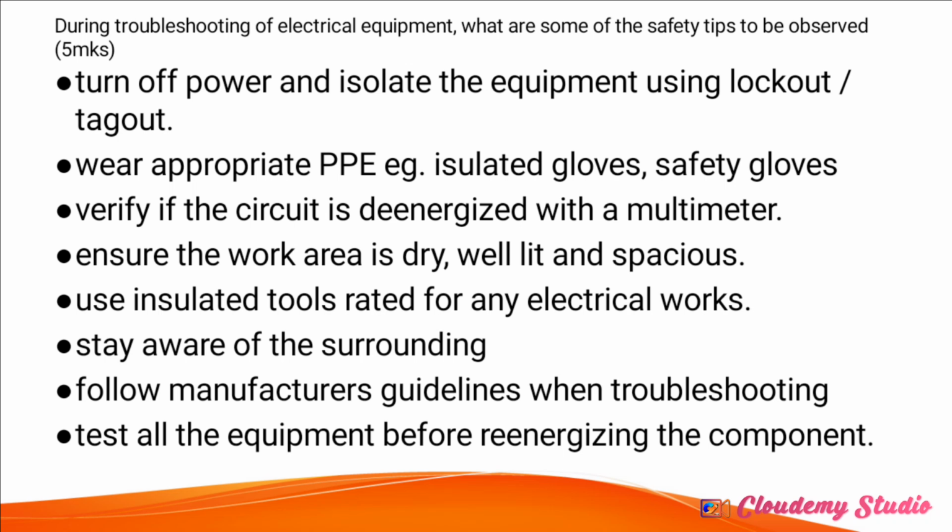So if you're looking at it from that perspective, as a maintenance person, that is what you should have in mind. Then next, of course, you have to wear the appropriate personal protective equipment. This is equipment that can reduce the level of death or potential hazards that might have adverse effects on you as technicians. Then you have to verify that the circuit is de-energized with a multimeter.